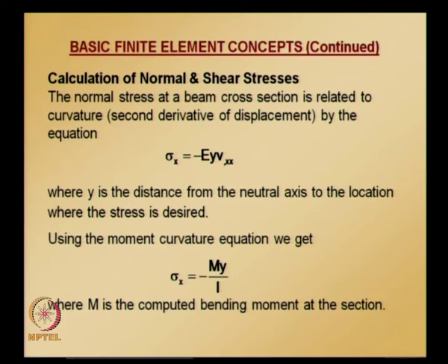So, whether it is a concentrated load or a distributed load, using finite elements we have seen how to calculate bending moments at any location in the beam. So, once we get the bending moment at any location in the beam, we can use this equation and get the normal stress. And now let us look at shear stress computation, and computation of shear stress is more complicated and depends on the shape of the cross section.